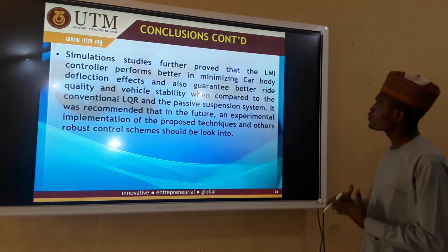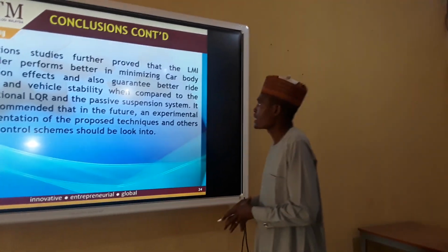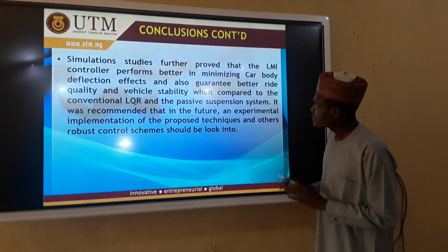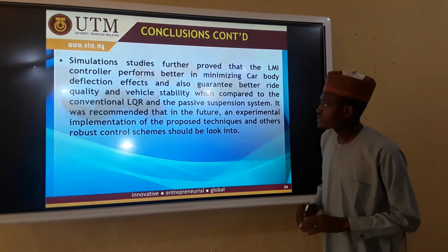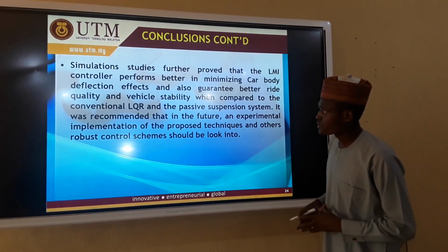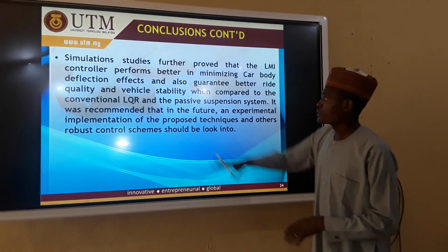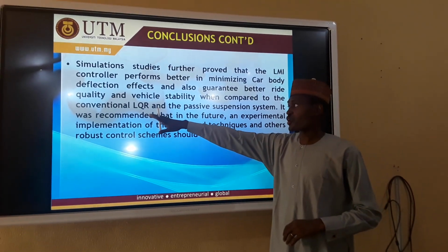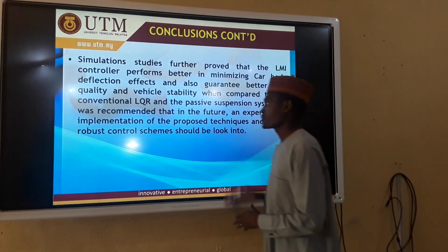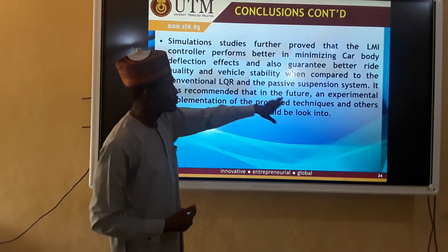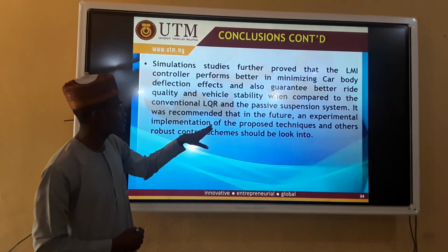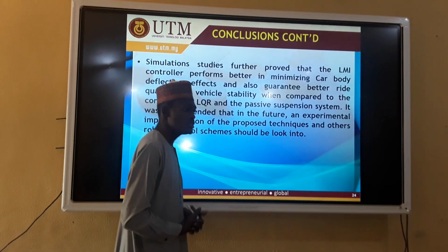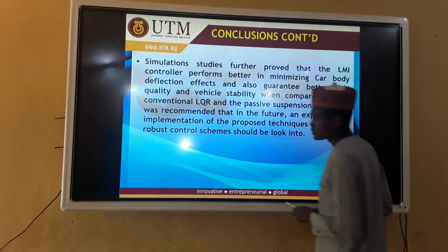Simulation studies further prove that the LMI controller performs better in terms of minimizing the car body deflection effects, and also guarantees better ride comfortability and quality, and better vehicle stability when compared to conventional LQR and the passive suspension system. It was recommended, therefore, that in future an experimental implementation of the proposed technique and other robust control schemes should be further explored.